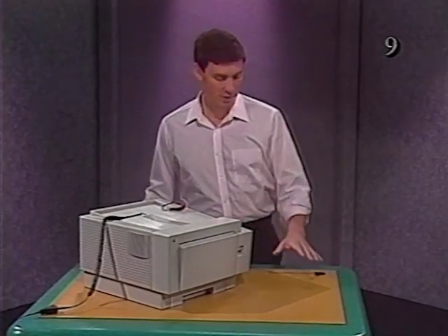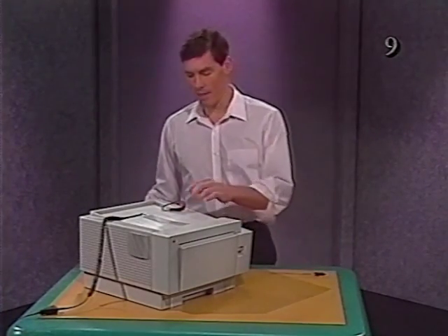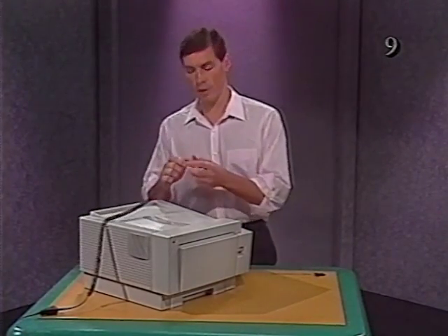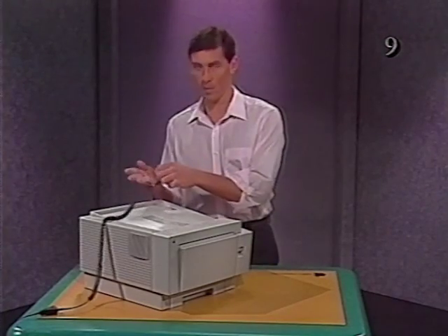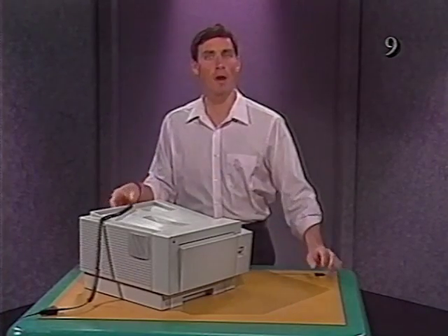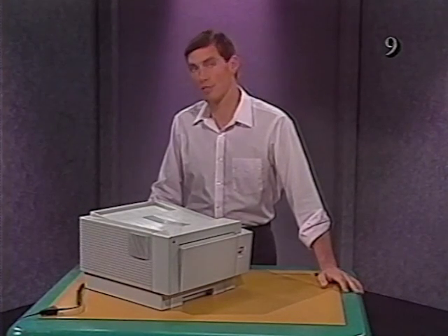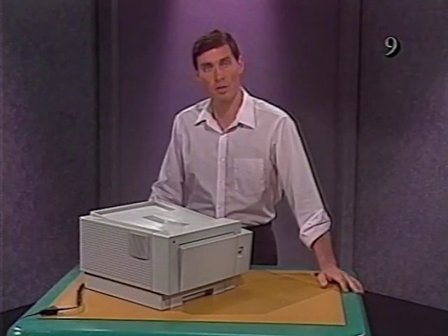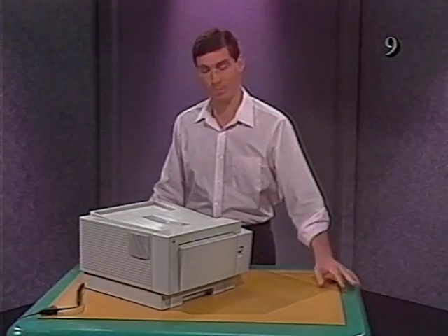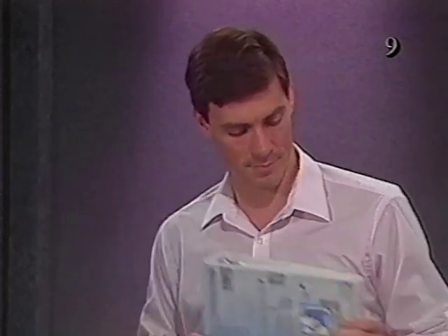Be sure your workstation has an ESD mat and that you always wear a wrist strap whenever you handle any PCB. Here's another important reminder. Preserve proper grounding and continuity by replacing silver screws with silver screws and black screws with black screws. Be sure to read the general information section of the Apple Personal LaserWriter technical procedures before you begin take apart.